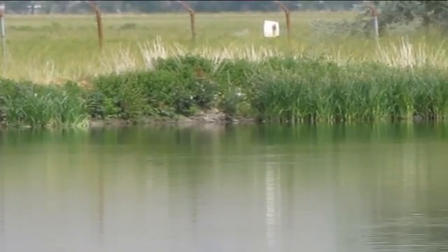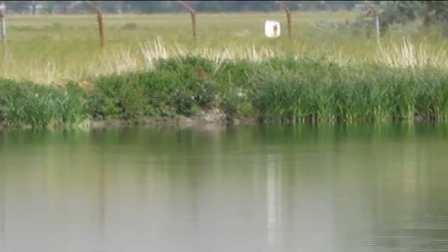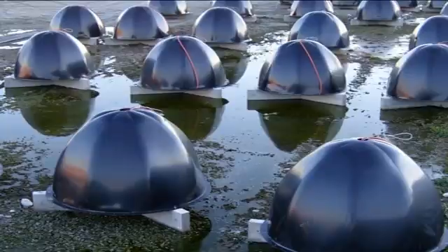Aerated lagoon system is another treatment plant employed in liquid waste treatment, which is generally used where there is not sufficient land available for seasonal retention or land application, and economics do not justify an anaerobic or activated sludge system. Efficient biological treatment can be achieved by use of an aerated lagoon system. Air is applied to these ponds by fixed or floating mechanical aerators or by compressors through air diffusers located on the bottom of the pond between 2.5 and 5 meter depth. Operating with 2 to 10 days retention time facilitates a reduction of BOD of 55 to 90%.